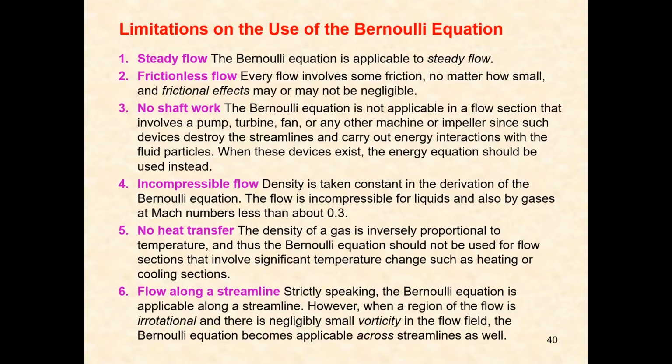Number 5, no heat transfer in the flow, because heat may cause natural flow due to the buoyancy effect on a less dense liquid. Number 6, it can only be used along a streamline.